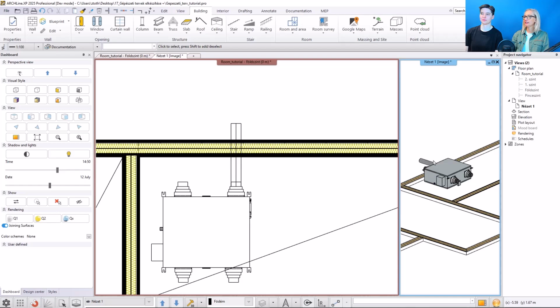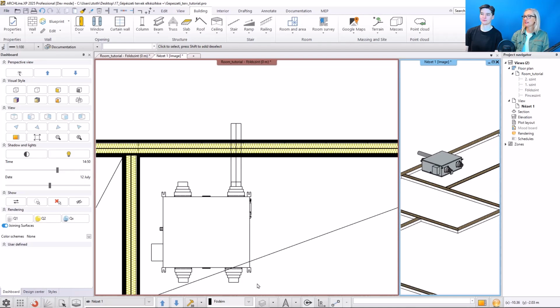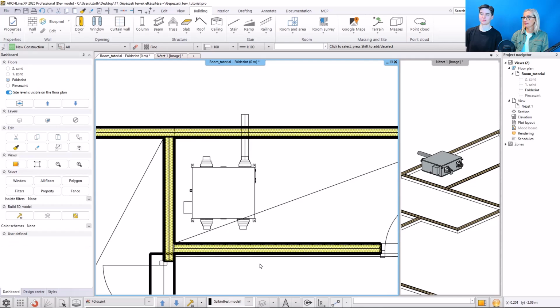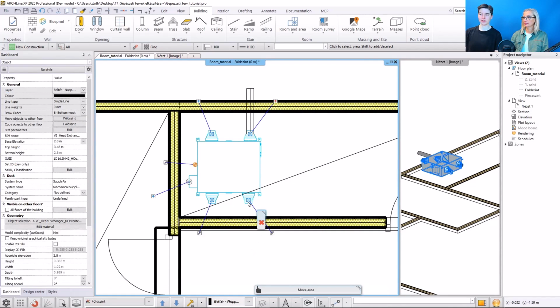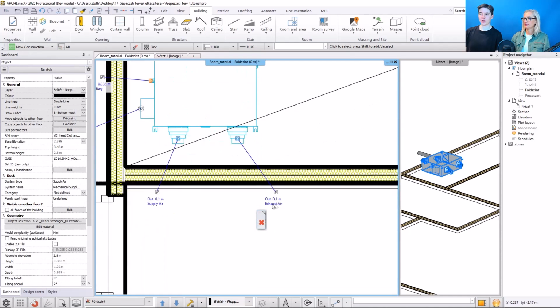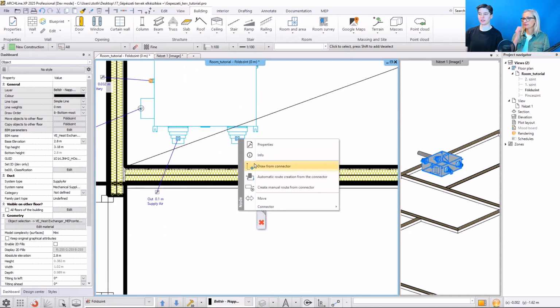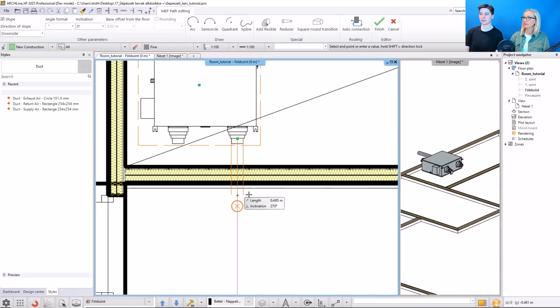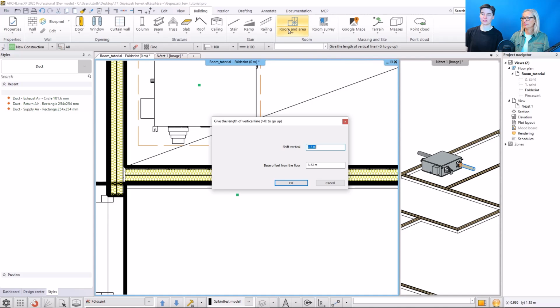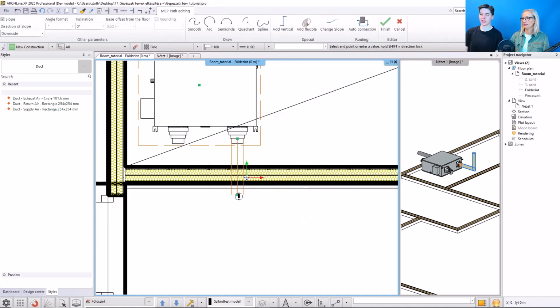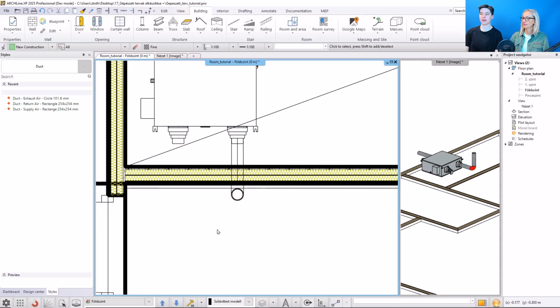Now let's create the exhaust pipe. This needs an elbow connection. Does that make it harder? Not at all. The program automates this. We start drawing the pipe horizontally, click to place a point, then choose to add the vertical segment, define its length, and confirm. As you can see, the elbow is automatically placed and matches the pipe's cross-section. What's next?